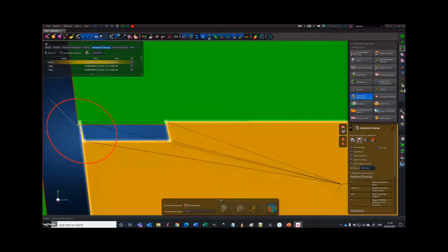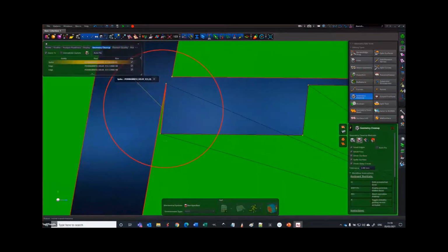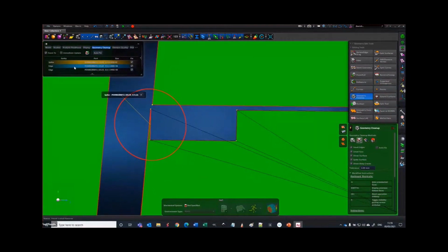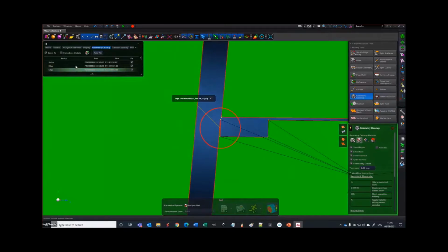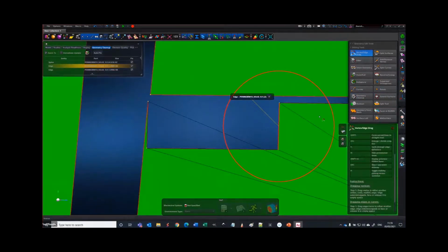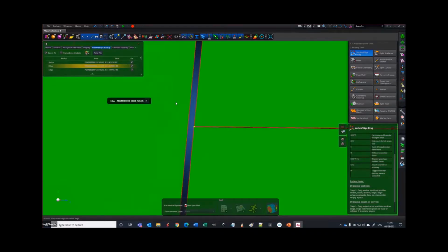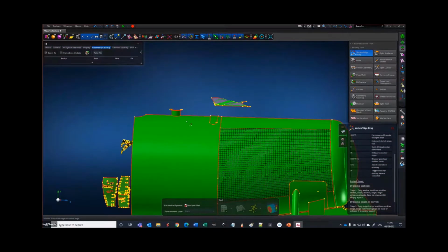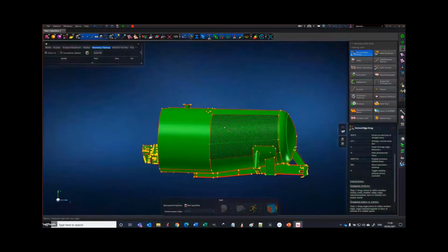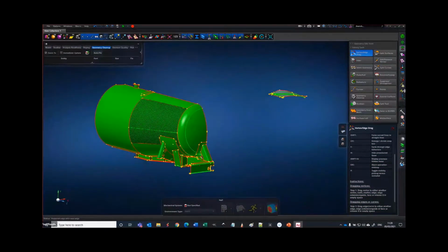And we can zoom in and find, okay, there we go. There's a little spike. So any feature that looks like this, it regards as a spike, and this is obviously causing us a problem. In this case, the short edges are shown in the exact same area, so we see one defect actually caused 3 defects. So using our edge drag tool, this is a very easy fix. We just drag this edge and snap it to that edge, and immediately our defects are gone. And if we refresh, we see that there's no defects anymore, and our mesh has properly updated along with it.